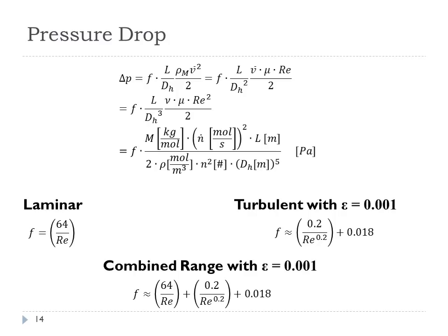So when we get to the optimization part of this course later on, we need to know both the area of the heat exchanger so we can estimate the cost, but we also need to know the delta P, because we need to know how much compression we're going to need to supply to overcome that delta P. So let's go through quickly how we'd estimate the pressure drop.